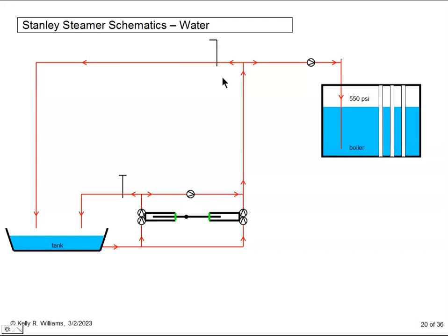Now, we've seen that we need to feed water to the boiler or not to maintain our 2/3 water level inside. But how do we know how much water is in there? The Stanleys couldn't just put a window in the side of the boiler. Not only would its structure have a weak spot, there wasn't any glass at the time that could withstand that pressure. And your window would be under the hood in the dark and hard to see from the driver's seat.